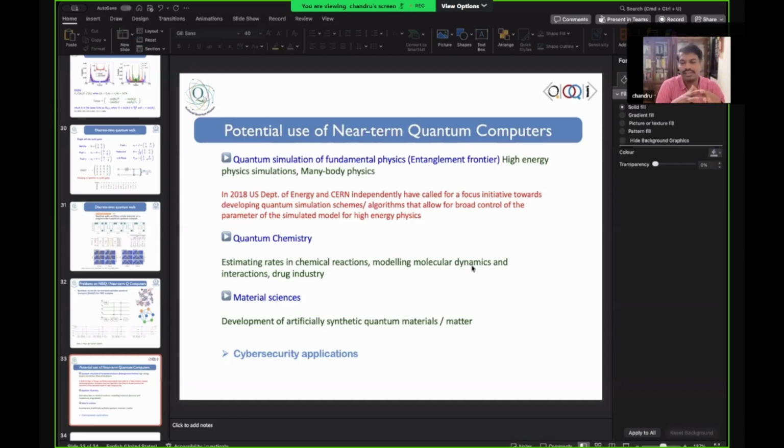As people who are close to the field, when we are trying to evaluate the claims, it has to be based on the results that come out as a test of it. So, for example, I can always configure a chip with hundreds of superconducting qubits, right? I can always design it, give it to a foundry, and get the chips. But that does not mean much for a computation, right? I need to take those chips and make them work. I should connect them all and then test every qubit's gate operation fidelity.